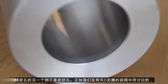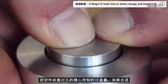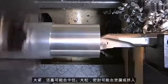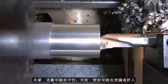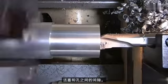Another example of a precision hole is a seal bore. As we discussed in our video on O-rings, seals rely on a carefully controlled amount of interference with the bore. If the fit is too tight, the piston could bind. Too loose, and the seal may leak or extrude into the gap between the piston and the bore.